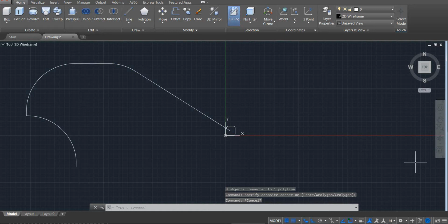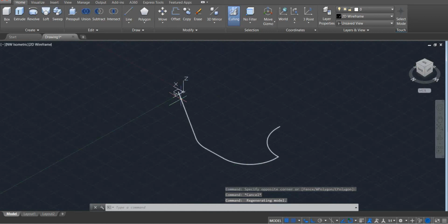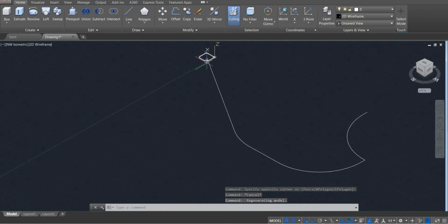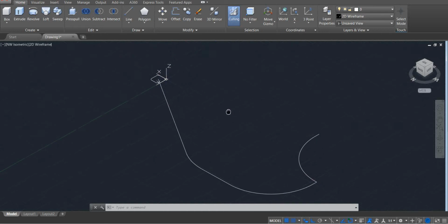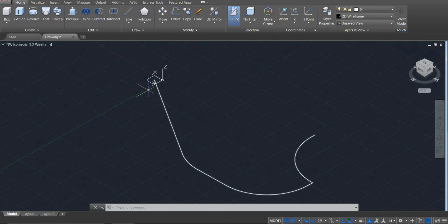So I should have two sketches. Going back again to the 3-dimensional view here, this should be the cross section, and this cross section should keep following this path. But as you can see, both of them, the path and the cross section, are located over the same plane. Make sense? Observe that both the sketch that will be extended and the path that this cross section will follow are located over the same plane.